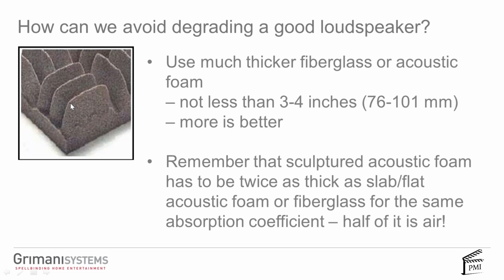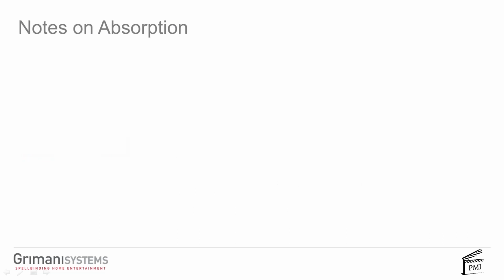The whole front wall. What radiates to the front wall is the low frequency of speakers. Speakers don't radiate mids and highs back from them. They radiate low, and they'll put 1-inch foam like this, which absorbs 2 kilohertz and up, on the wall behind the speakers, and it has no effect to the back of the speakers. All that it does is capture a reflection after it's passed your head, bounced off the back wall, come back, and absorb only 2 kilohertz and above. Total waste of time. It makes it look very, very pro, but it actually doesn't work. It hurts for nothing.